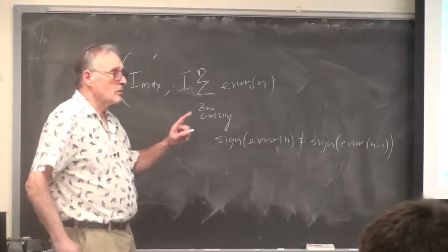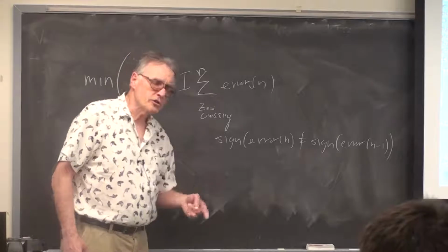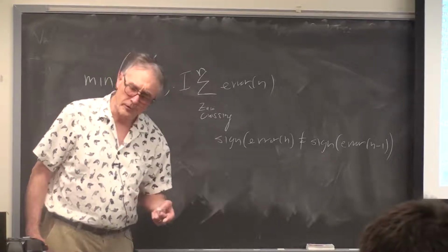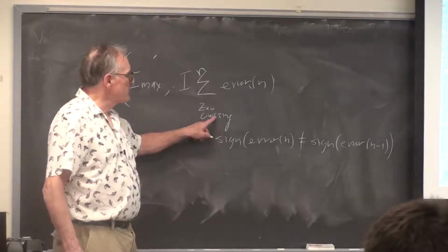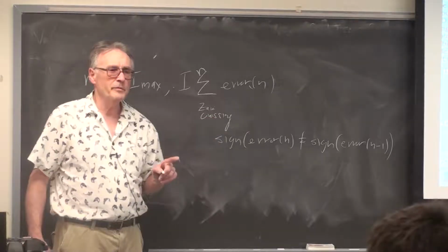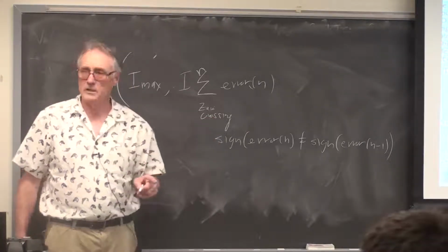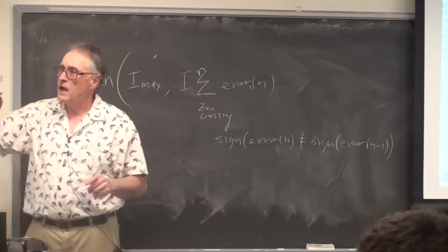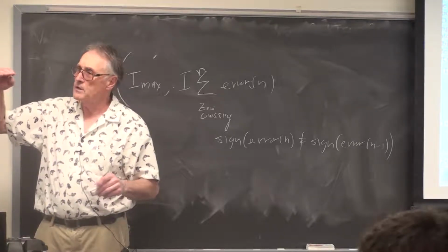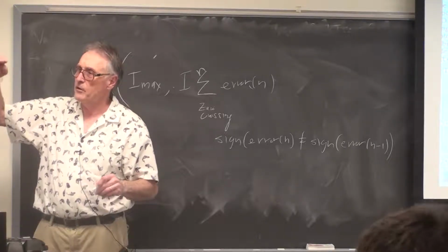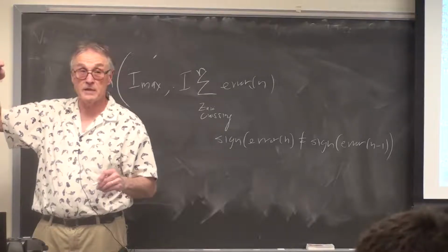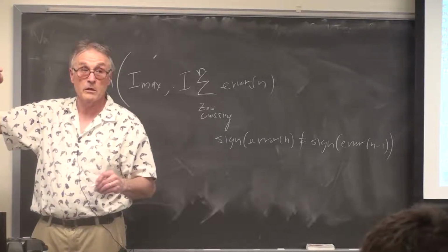So now, what should you set the integral to when there's a zero crossing? One possibility would be to zero it at zero crossing. Say, I've built up to 0. I'm going to zero the integral term if we go a little bit high. That'll certainly stop it from increasing anymore.